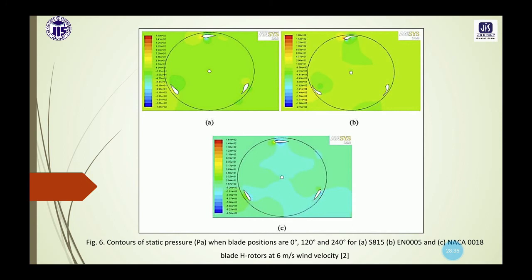These real life problems are basically turbulent in nature, and so some suitable turbulence model needs to be chosen. In the software there is the option to choose the suitable turbulence model. There we will see various turbulence models known as K epsilon, then K omega, where K is the turbulent kinetic energy, epsilon is turbulent dissipation rate, omega is specific dissipation rate, then SST K omega, which is shear stress transport K omega model.